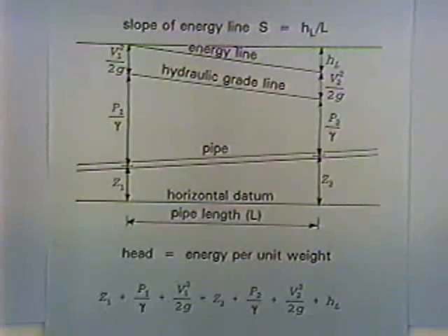As water flows, the turbulence of the water, the resistance of the pipe holding the water back causes some of that hydraulic energy to be lost to the environment as heat. And to us, as a civil engineer, that's an energy loss. It's lost for our purposes, and head losses are a key term. And so we've reproduced the energy equation here on the bottom of the sheet.